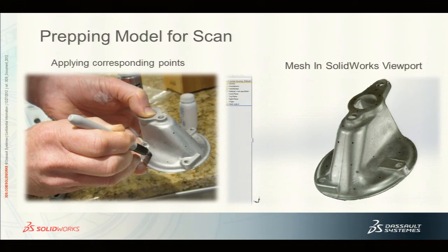Okay. The next step, for laser scanning and in particular the Next Engine scanner, is this: it has a rotating table and takes several scans 360 degrees around the object. To put all that together, the user gets involved a bit, aligning those different scans into one mesh and then fusing it into a single mesh. That's what I'm doing here. I'm taking a Sharpie marker and putting down what are called correspondence points. They're very helpful when I start aligning this scan pass with that scan pass. I say, connect the dots.